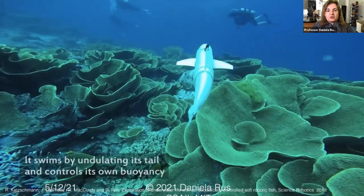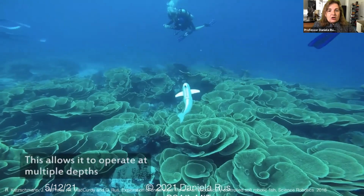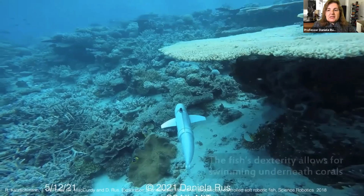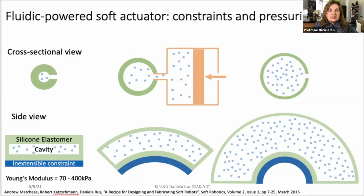For example, Sophie, the soft robotic fish I already introduced, is an example of such a robot. The robot has a tail that undulates and helps propel the robot forward. It also has dive planes that control the swimming depth. And so I'd like to explain soft in the context of the tail of the robot. The tail of the robot is enabled by something we call fluidic power soft actuation. And fluidic power soft actuation essentially consists of a cavity that is augmented with an inextensible constraint. The cavity can expand when we put fluid in it, air or water or any other form of fluidic substance. Because there is the inextensible constraint, as we put fluid inside this cavity, it expands, it forms a curvature, and by controlling this curvature, we can control the shape of the robot.